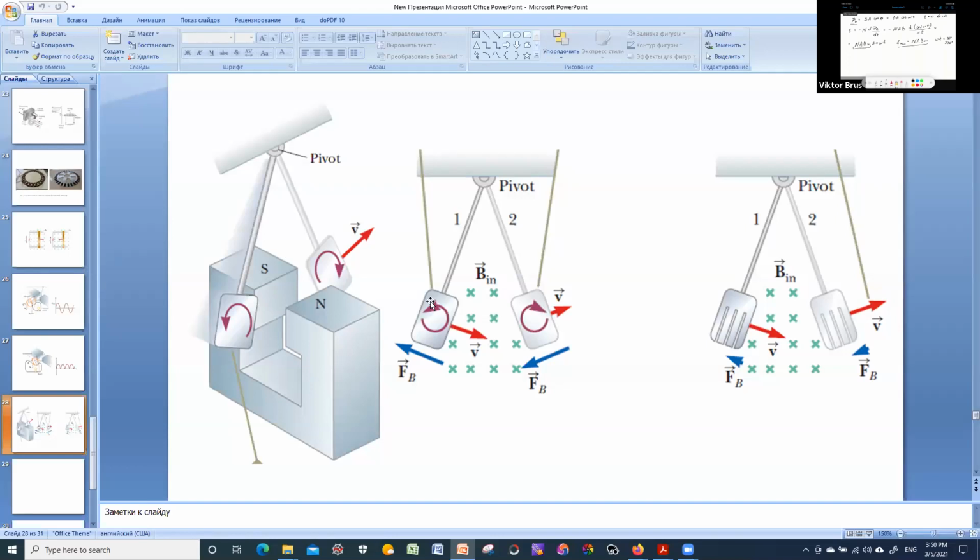They are made of continuous metal disc, which is spinning with quite high angular velocity. And if we run some current through electromagnets located next to this conducting metal wheel, then generated eddy currents will result in attenuation, like slowing down this motion.